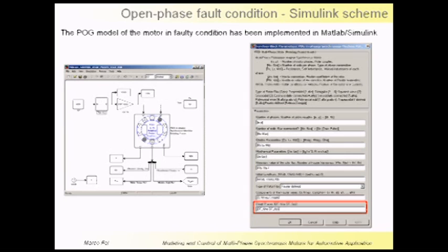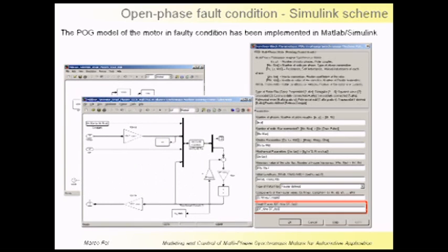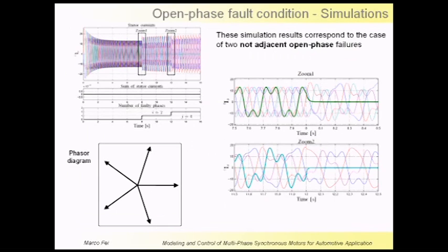Inside of this block, you can see the electrical part of the system. Also, in this case, there is a direct correspondence between the Simulink scheme and the POG. This is the simulation obtained for a 5-phase synchronous motor when two non-adjacent open phase failures occur.